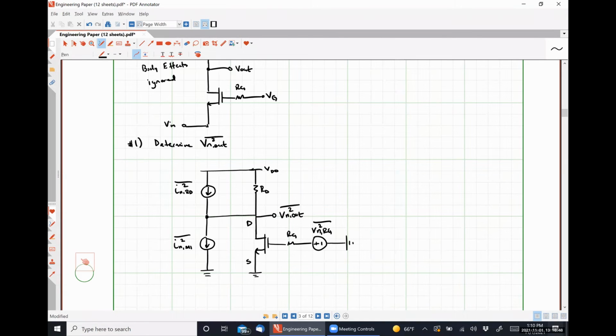Whole goal of this transistor here, if we work this thing with all of the other sources turned off, this is serving as our input voltage for this amplifier, right? So it should make sense that if we're not worried about the drain resistor noise and we're not worried about the transistor noise, this noise will get converted into a current flowing between the drain and the source, because that's exactly what the transistor does, is converts that input voltage into a drain current. That drain current will then flow through that resistor RD, generating some output noise.